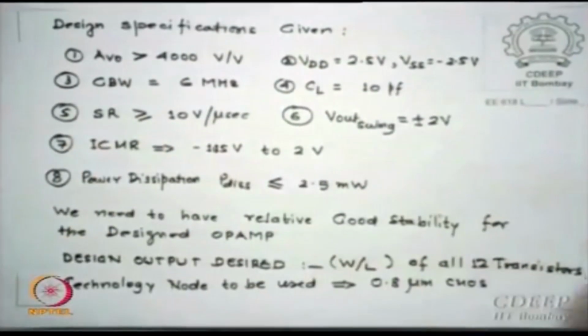So I have now a parameter which I can play with. Okay, for some other specs to meet, I figure out that AV0 should be 4500, so I will put 4500, because the design says it should not be less than 4000. So I meet those specs anyway. But once I designed it, once I got it, those specs are fixed. Once the chip is done, then it is not changed again and again, okay. Till you fix, you have the parameter to vary.